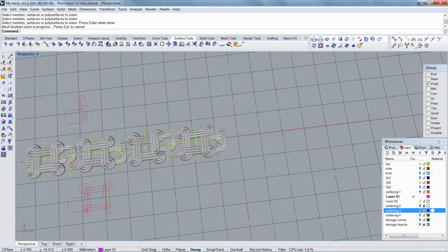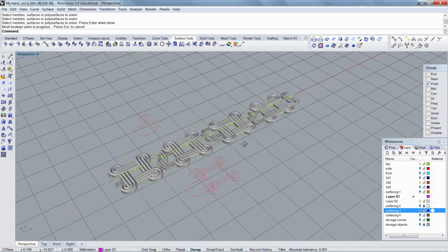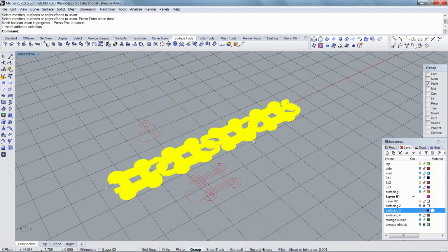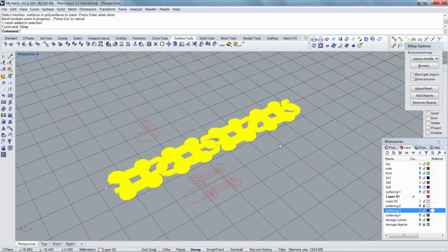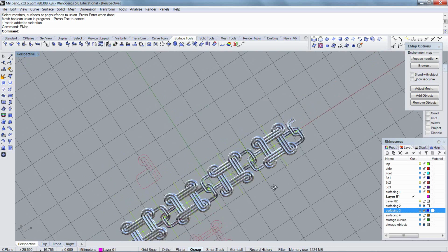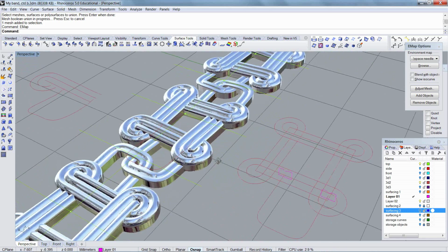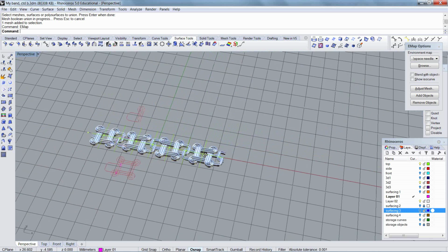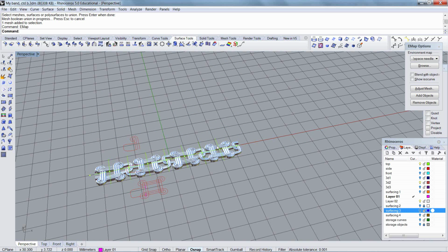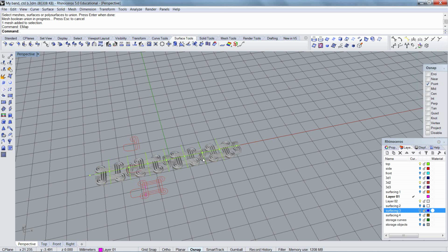All I have left to do with it is to flow it. I will emap it first so we can take a look at it flat. E-mapping will be very fast because it's already a mesh. Usually when you hit E-map or shade, Rhino has to generate the mesh for you to look at, but when you're dealing with a mesh object already, there's no mesh to be generated.